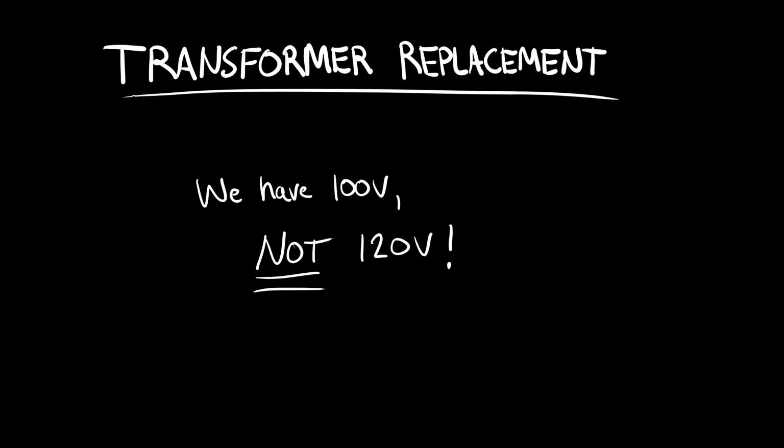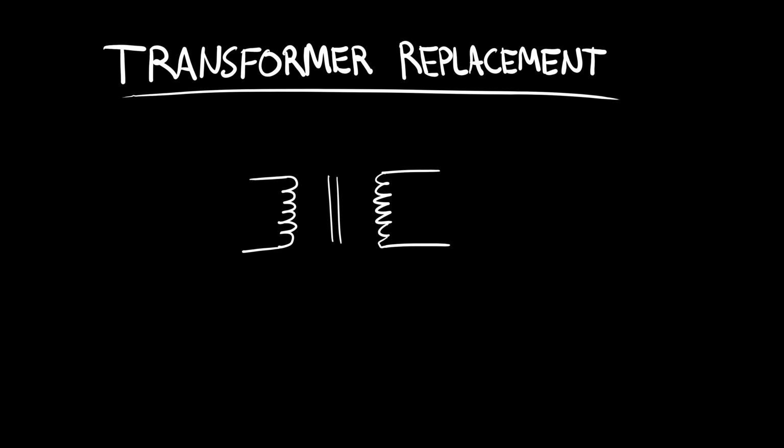There was one hiccup though. Remember that this is a 100 volt machine and most transformers are rated for 120 volts. This complicates the process of sourcing replacements, because a 120 to 12 volt transformer becomes a 100 to 10 volt transformer instead. I had to account for that.